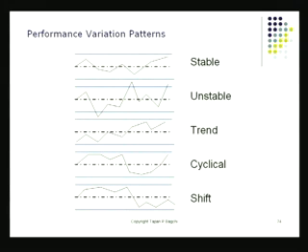Now, what happens after you plot the chart? You find some unusual patterns. One very simple signal that you get out of a process is that one of those data points went beyond the control limit. That's one signal out of a control chart. It can happen on an X bar chart, and it can also happen on an R chart. Both of those charts can actually give a signal. What we have to do is see whether we can get more signals out of the same chart. I need not really wait till I get a point beyond control limits.